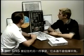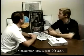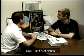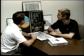The other thing to remember about SRS is that it will never command a level flight. It'll give you at least 120 feet per minute climb. And then the last scenario would be on a go-around. It'll give you V approach or whatever your current airspeed, whichever is higher.